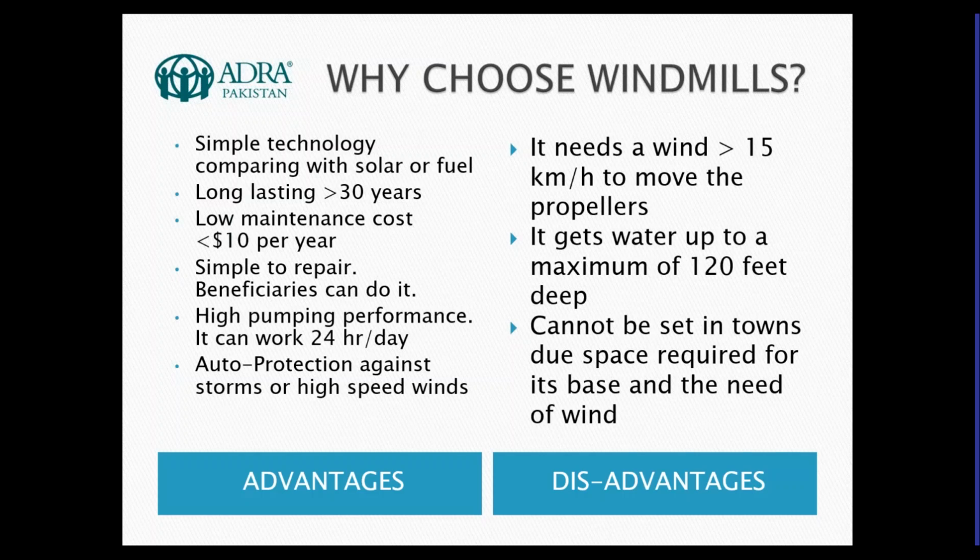And also because of the space and the wind that it needs, it's very difficult to set the windmill in the middle of the city or the town, where the houses and the trees make a barrier against the wind, and then the propeller will not move. Also the space, because the base has a surface to cover, and maybe in a city it will be a little bit difficult to set. But for rural areas, there is no problem.